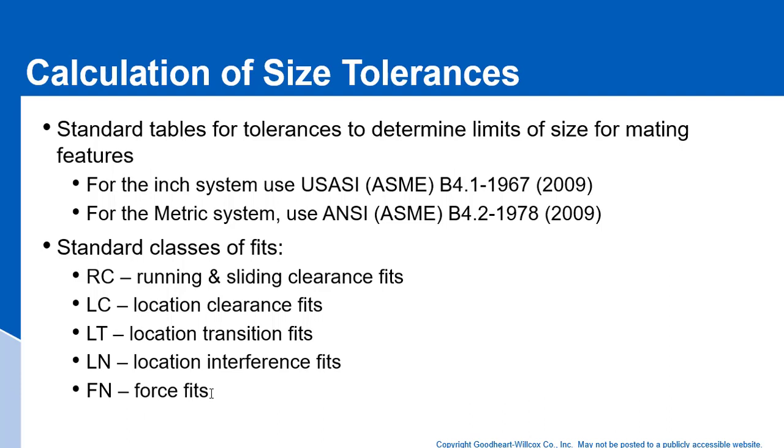Those fits in manufacturing are typically achieved by freezing the shaft and then heating up the wheel to use the coefficient of thermal expansion to your advantage and cause a situation where the parts will go together almost like a clearance fit, but after they have achieved steady state in terms of the temperature of the parts, then you'll have an interference or force fit.